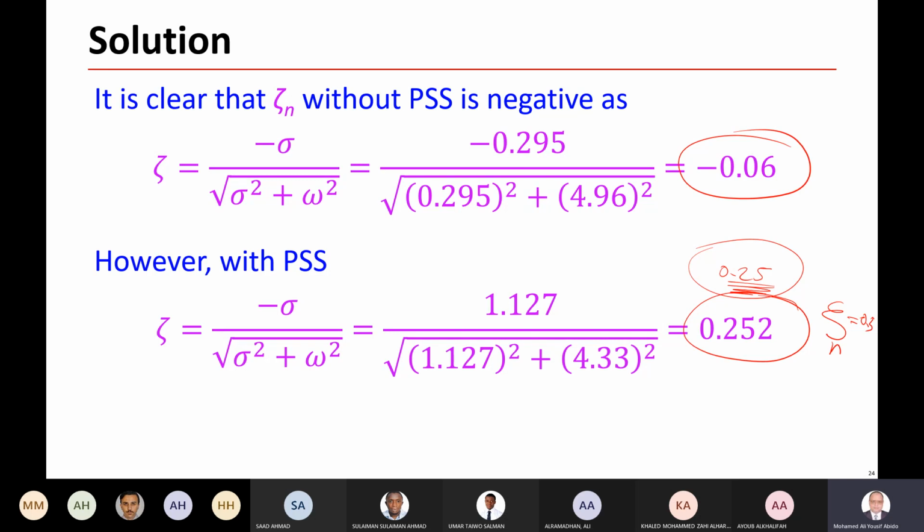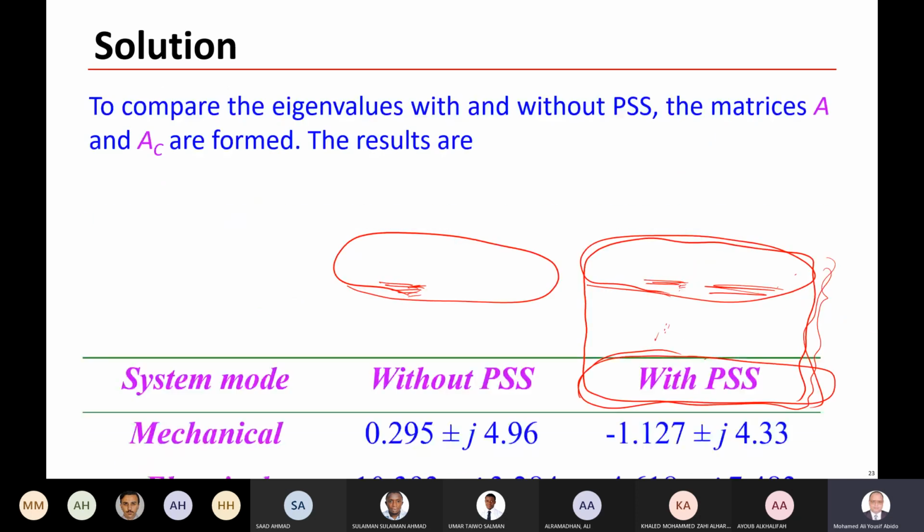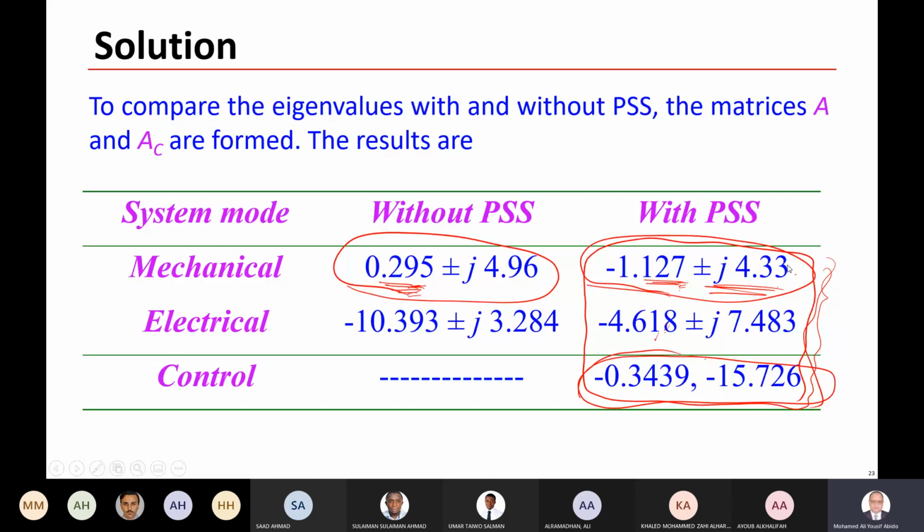Of course, we expect some drift. We call it eigenvalue drift, and we assume a certain damping coefficient, but after design, we have interaction between these modes together. We don't have only that mode in the system.